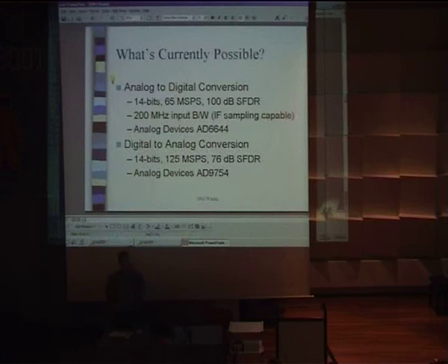You're okay. But what you can do, start thinking about what you can do with 65 million samples per second. There's a Nyquist theorem that says minimally you need twice as many samples per second as you have bandwidth of interest. And if you want a little engineering margin, you cut this down to like 50 megasamples per second, which could really deal with 25 megahertz worth of bandwidth all at one time.